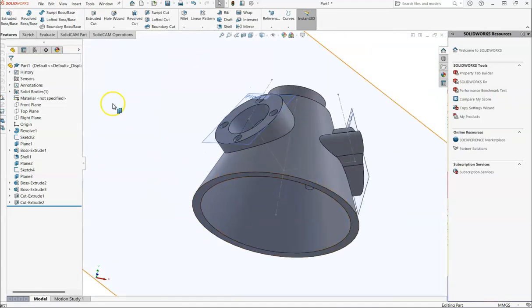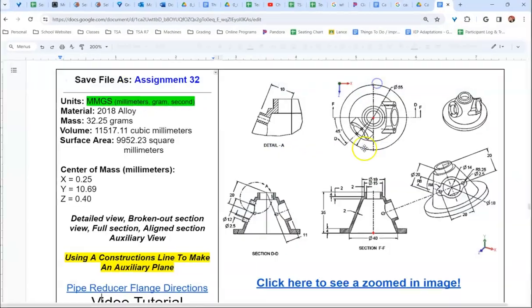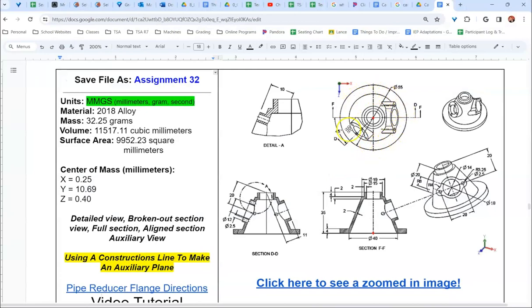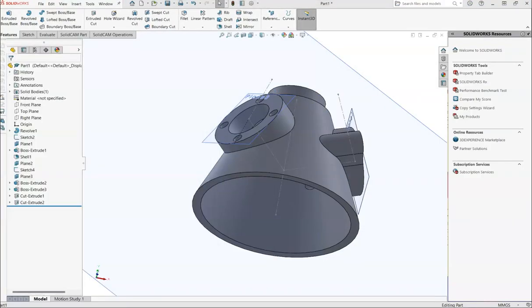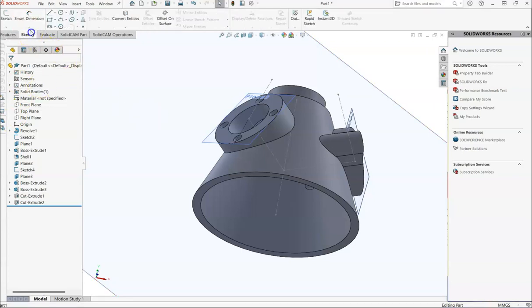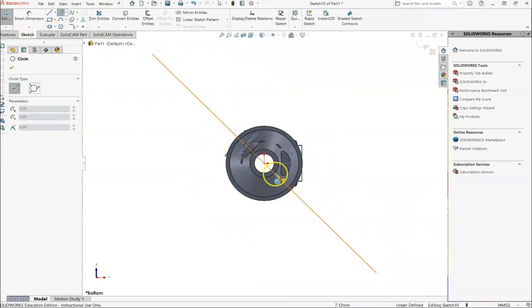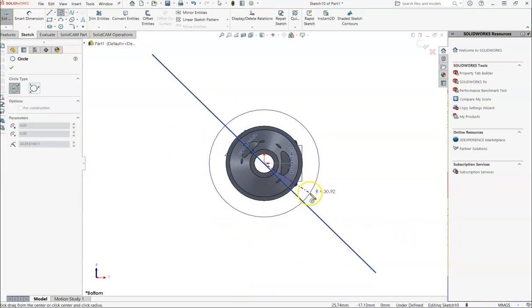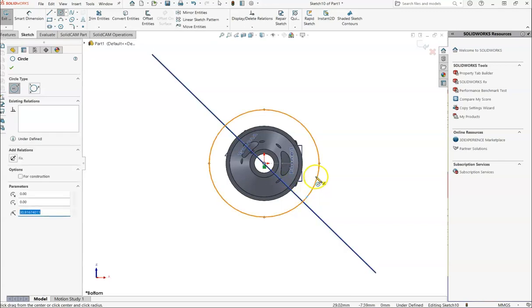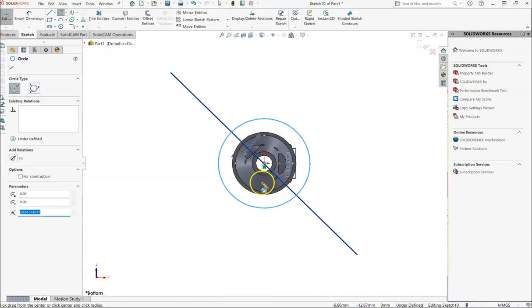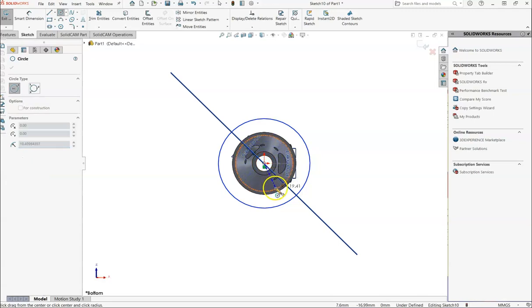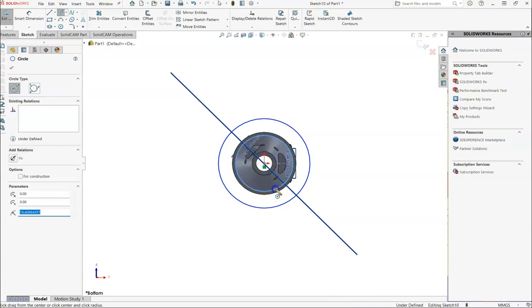Now we're going to, on the bottom here, make that extra piece, that bottom piece. Get your sketch tool, the bottom of this. Get our circle tool. We're going to draw a big circle out like this. If we just did the overall size here and extruded it up, we'd be extruding through this bottom part too. So we actually need to make 2 circles. So you're going to draw from there to this inside ring. Okay, not the outside, the inside ring.